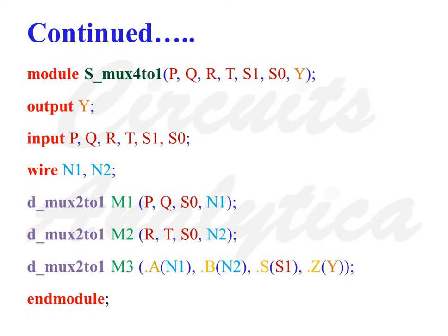So you compare the three instantiations. In the first two component instantiations, the type of association of the ports of the 2:1 multiplexer is positional association. Based on the position of the ports, we have connected the ports or signals of the circuit under consideration.